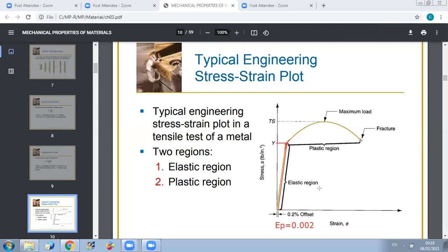First, in the elastic region, the modulus of elasticity is enough to define the behavior because sigma is E times epsilon. On the other hand, in this part, it's different. It's a different equation. First, it's clear that it's not linear anymore, okay? And we will see together what the equation of such parts is, how we can find its equation.